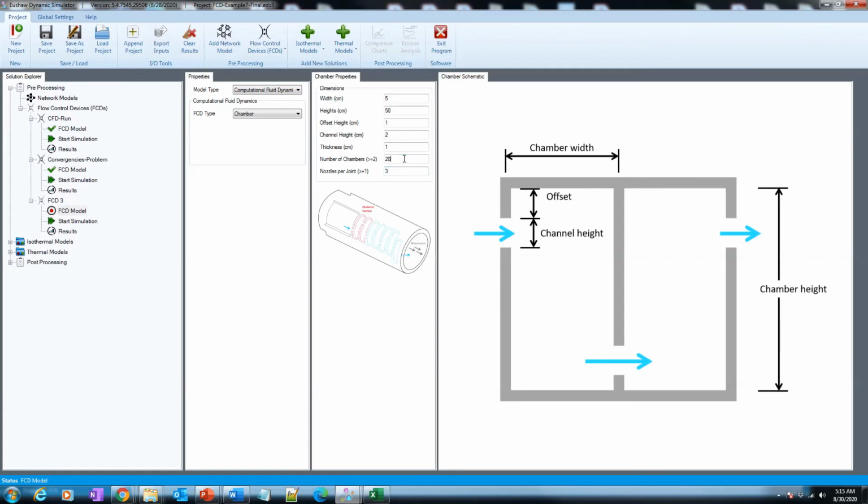So the software takes this chamber or this series of chambers and runs it for a series of Reynolds numbers or a series of velocities that you get into this chamber to calculate the pressure loss coefficient or the resistance factor, because that's Reynolds dependent, and for one flow you only have one Reynolds.